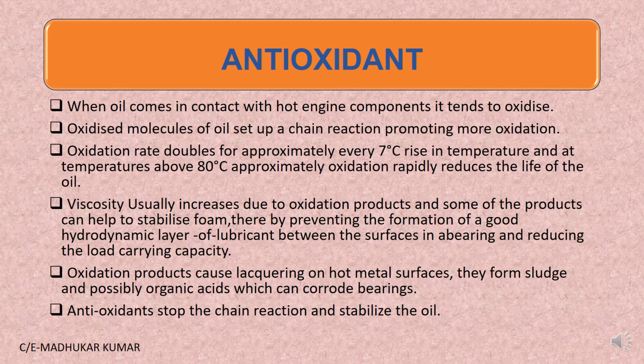Now another lube oil additive, the antioxidant. When the oil comes in contact with the hot engine components, it tends to oxidize. Basically, it is a normal thing. And these oxidized molecules of oil set up a chain reaction, promoting more and more oxidation. If this happens, the actual lube oil property will be lost.